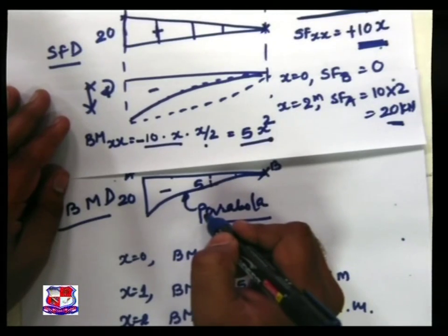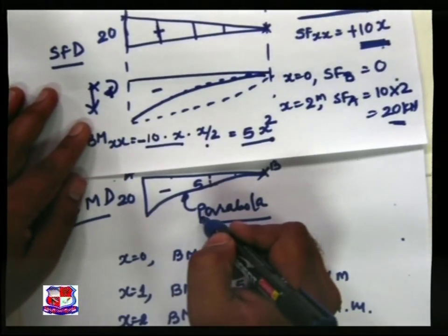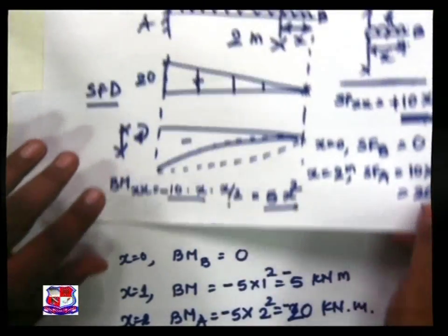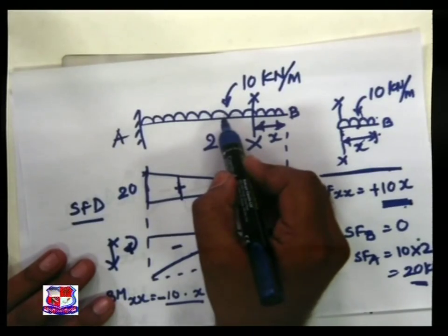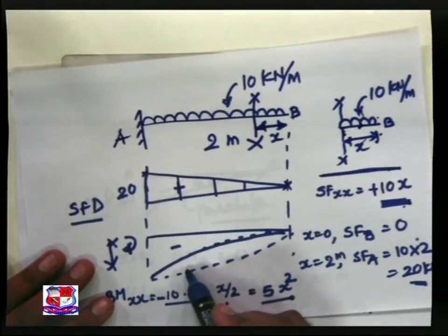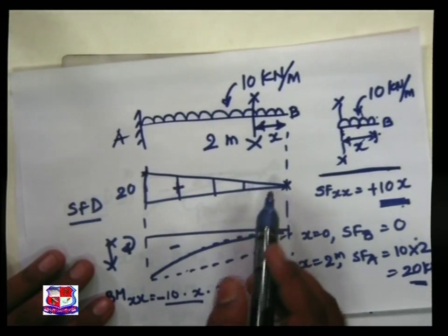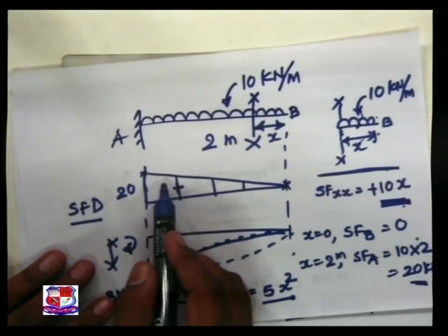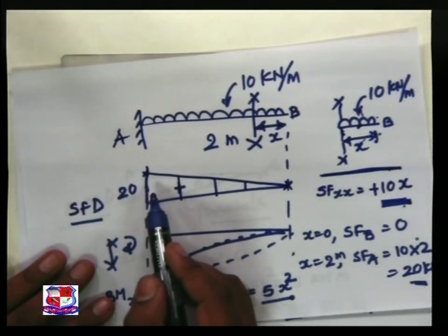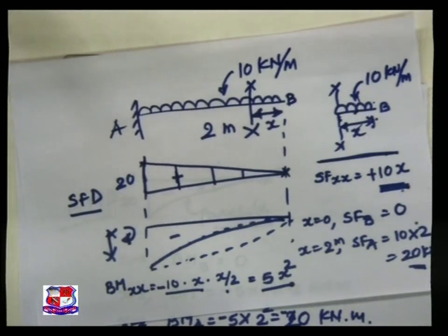We follow the same rule that we used in the case of a simply supported beam. For a beam with UDL, the variation of the bending moment diagram is given by a parabola, and the shear force diagram is shown by an inclined straight line. The same rule is applicable for a cantilever beam. So the same case you can visualize over here in this PPT.